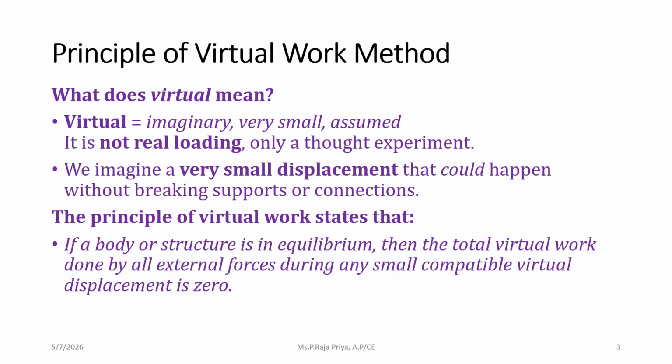Before going into the virtual work method, that is the principle of virtual work method, we'll first go through what is called virtual work and what the principle states. Virtual is something which is not real, that is imaginary or something which is assumed. Here we imagine a very small displacement that could happen, but without breaking the support or the connections or joints.